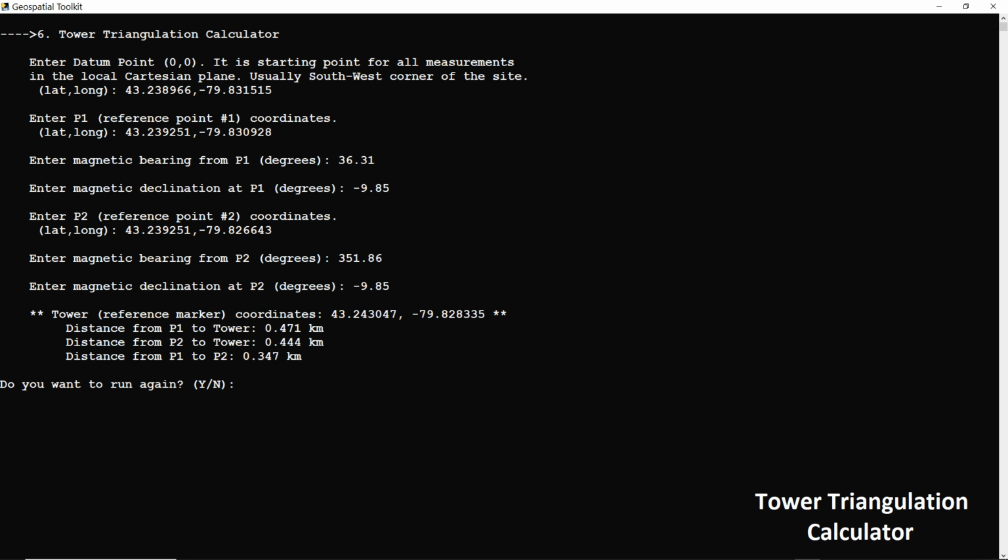For small areas, up to 10 km radius, the curvature of the Earth introduces negligible distortion, sub-millimeter level, which is generally acceptable for construction projects. Beyond 10 km to 20 km, the curvature starts affecting accuracy with discrepancies growing to several centimeters, depending on the project's requirements.